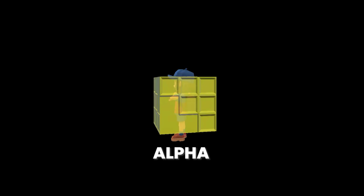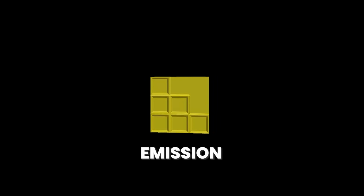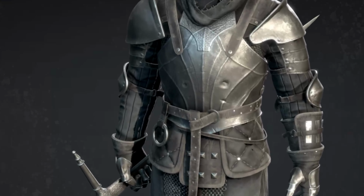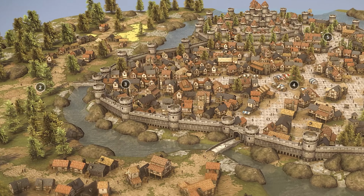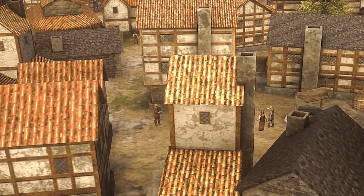Alpha, transparency. Ambient occlusion, fake shadows in tight spots. Emission, makes it glow. Displacement or height map usually changes the shape. These maps can add scratches, volume, soft shadows, even glowing effects, all while keeping the mesh untouched. And that's huge for performance. With the right maps, you get realism without overloading the game.